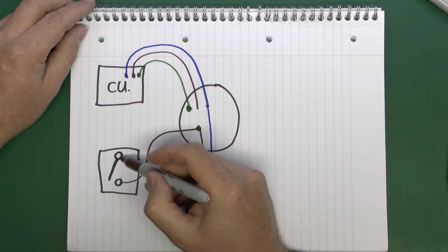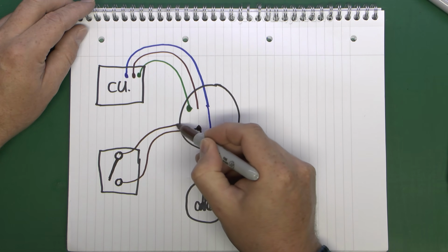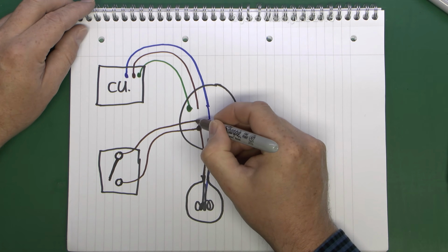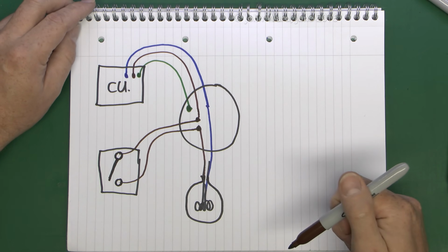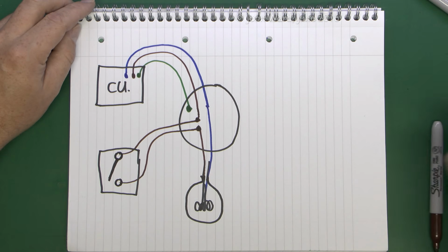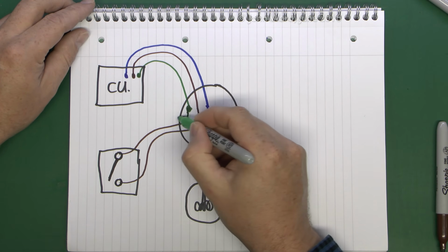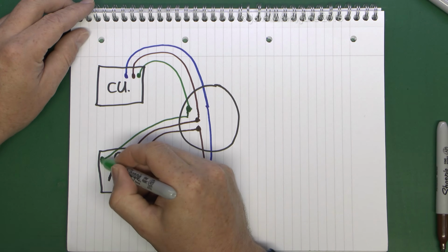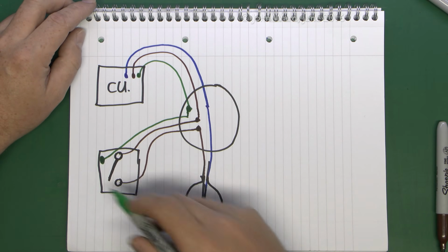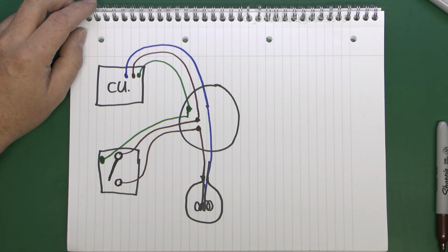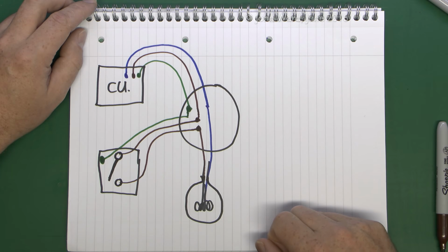And the other one from here as well. And again, it'll be part of the same cable there. We can join that one onto the mains wire that comes in. And typically you would have the earth wire going down there as well. That would be connected to the metal frame of the switch if it's metal, or just parked in the back of the box if it was a plastic one.